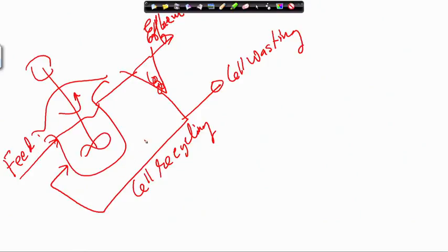Now, suppose this is the settled cell mass concentration XU, and this is X. When you settle, obviously the cell mass concentration will be more here, and this is the settled cell mass concentration. Let us assume the recycle flow rate is Fr, and this is F0. Then what will be here? Flow rate F0 plus Fr. Am I right?